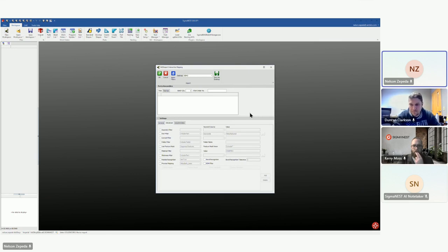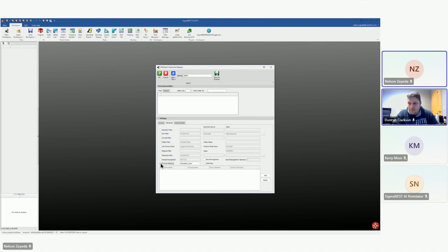I was not using these for any of your models, but generally speaking, you can use the custom property fields in the SolidWorks parts to do part filtering. So if you need your plate parts and you want to make sure it's only the plate parts coming in, you could set up a custom property field, just labeled plate, and that's how we can make sure, without question, that it's coming in appropriately. There's other things in here. You could do material filtering, thickness filtering, that kind of stuff.